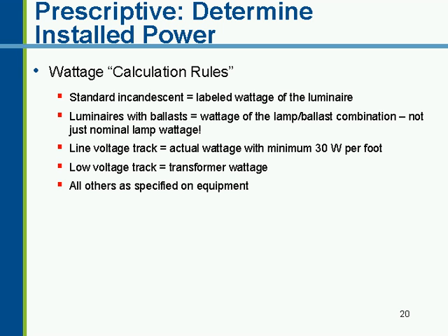If you have any luminaires that are driven by ballast, fluorescent, HIDs, etc., it's the wattage of the lamp and ballast combination, not just the nominal lamp wattage that you have to use. It's very important. You can't use nominal values. It has to be lamp and ballast combinations.